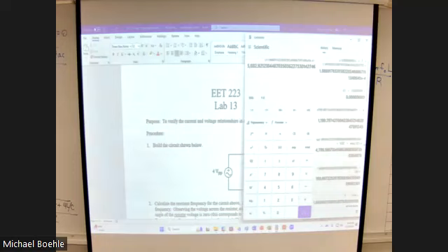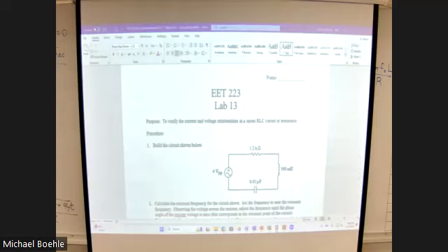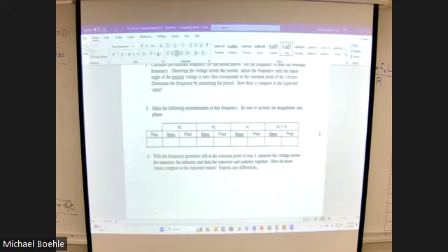Right? Oh no, actually I do tell you to calculate it. Oh, never mind. I just did step 2 for you. Well, part of step 2. Okay. And I think I told you that just so that you would be able to get close to it. So set it near it, and then watch the voltage across the resistor and look for that 0 phase shift. All right, because when that phase shift is 0, you're good. That is resonance. Then you're going to determine what that frequency is off the dial as best you can, probably as accurate as you need.